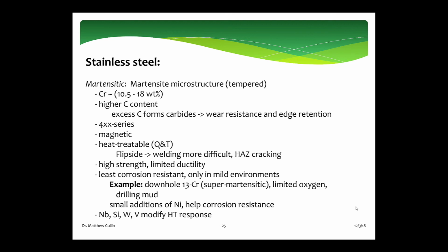Generally it's being exposed to drilling mud and very limited oxygen. A lot of times it's hydrocarbons, not as much water, and hydrocarbons are not a good electrolyte, so they tend not to be corrosive. That's your oil. But yeah, the limited oxygen is a really big determining factor.